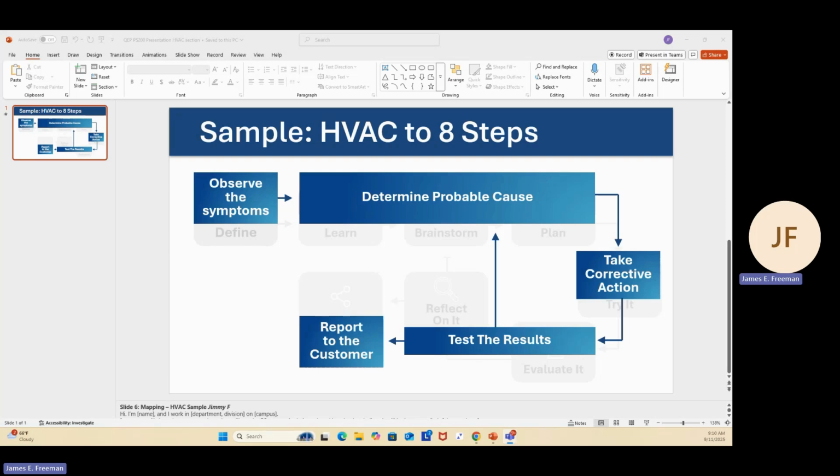We try to break this down into three categories. Is this a mechanical problem? Is it an electrical problem? Or is it a design problem? Once we determine if it's mechanical, electrical, or design, let's say this is an electrical problem, then we use the sequence of operation of how the system should operate correctly electrically: what could be causing what we're seeing here that differs from a normal operation, and what test instruments do we need to troubleshoot to find out where our problem is.